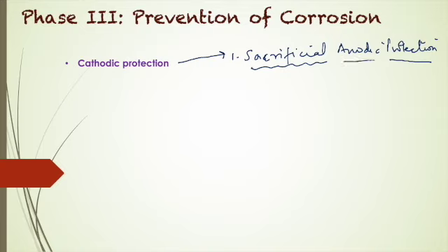By behaving like an anode, because you know anode corrodes, and anode is the one who is sacrificing everywhere in the corrosion. So the metal structure can be saved from corrosion by connecting it with a wire to a more active metal, so that the corrosion is concentrated at the more active metal piece, and as the more active metal is sacrificed in the process of saving the metal from corrosion, we call it a sacrificial anode.